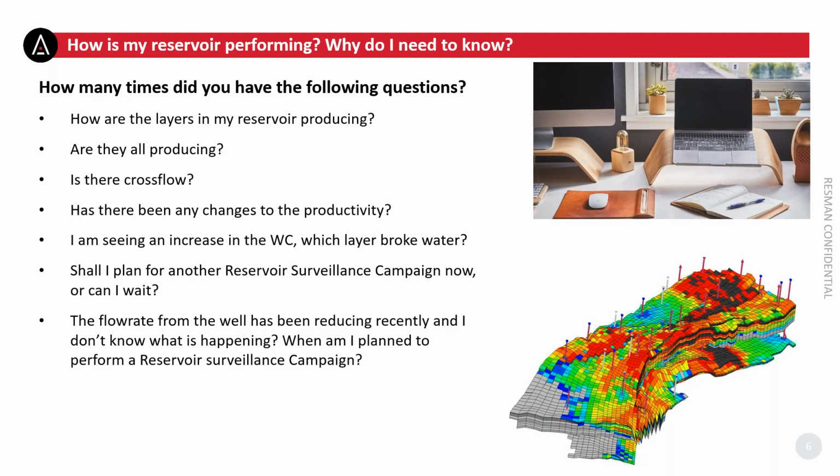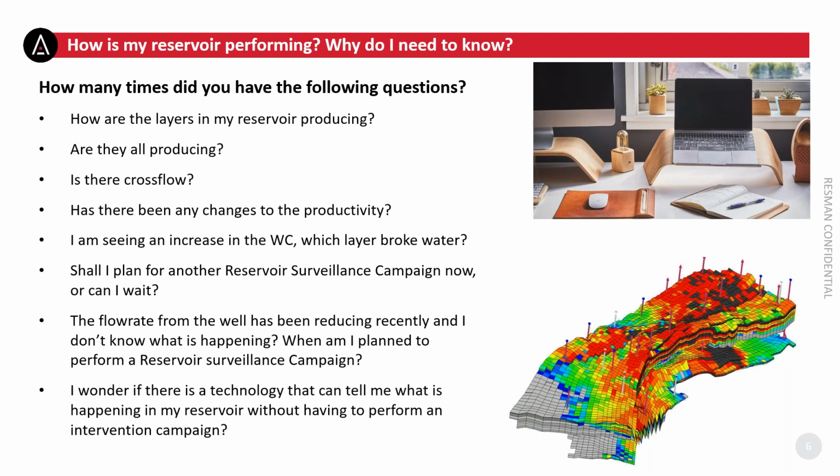The question that comes up into my mind, and which we always think about, is that I want to perform a PLT run, for example, or I want to do a surveillance, but then I don't know when to go and take that action. And to know when to take that action is, obviously, you want to know, am I seeing any changes happening on my wellbore that gives me, let me say, the good justification for me to go and perform a surveillance in the well. So all of these questions that come in my mind are questions that you'll always be sitting and thinking, how can I get these questions answered?